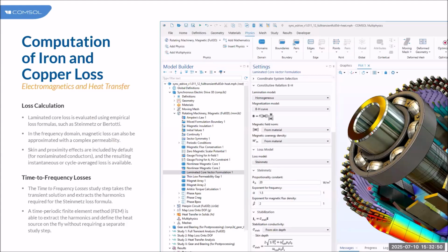So those losses will be directly coupled to the heat transfer module available in COMSOL. This particular machine is a synchronous motor drive, or there is a synchronous motor part. Along with that, using the electric circuit module available, it is becoming a complete electric drive, connected to the outside circuit, and you have a synchronous motor here, as shown in this figure. Now, when it comes to the material properties, some of the property parts will depend on temperature. So we have to couple that as well.